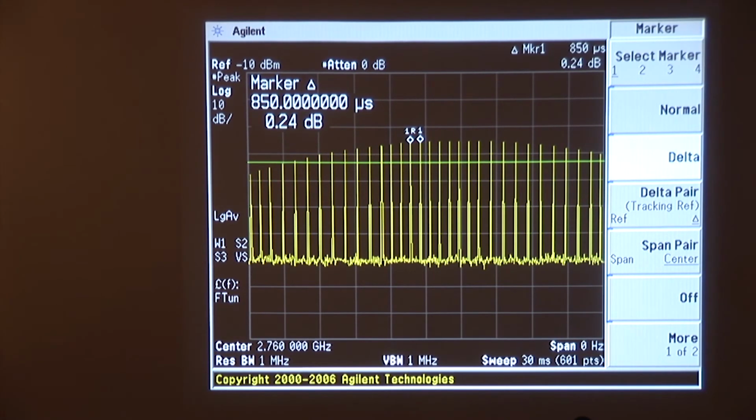All right, now we would note and we would record this pulse sequence as part of our measurement set on the radar, and we would note this so-called stagger sequence of intervals, which we could also play back out of the data later, having recorded it. Now let's zoom in one more time. Let's zoom in on an individual pulse inside the sequence and measure the pulse directly.